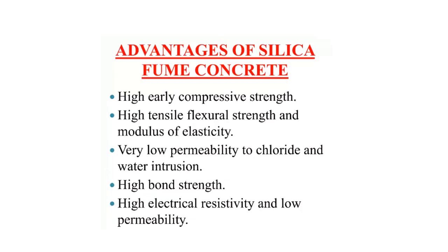Some of the advantages of silica fume concrete: it has high early compressive strength, high tensile and flexural strength and modulus of elasticity, very low permeability to chloride and water intrusion, high bond strength, high electrical resistivity and low permeability.